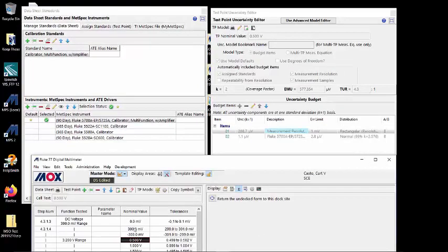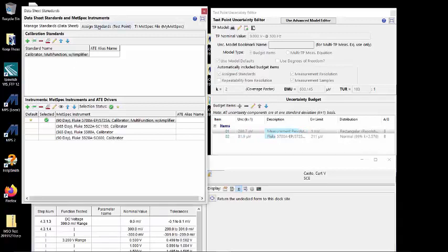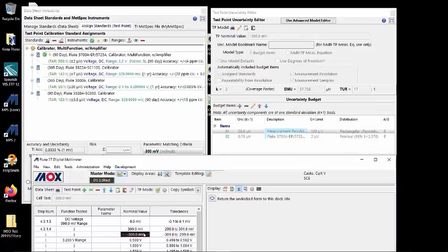And then if you remember what I told you about using the Alt and the arrow keys for the grid, if I move down test points, you can see that both of those forms are updating as I move through the test points. Well, there's really nothing to see on the left one, so let me switch to a tab that changes with the test points. Okay, so now you can see as I'm moving up and down the test points, both of those forms are changing or updating because they're, again, tied to the currently active test point. As I told you, that's really a key concept in MPS, is that most of the user interface is driven around which test point is currently selected.